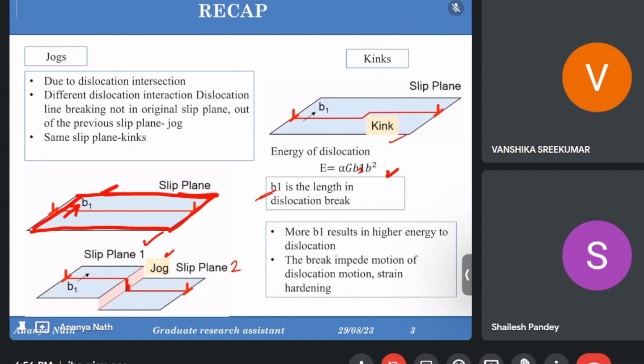Through the interaction of the dislocations, generally they lock each other, which is called the Lomer-Cottrell locks, by penetrating each other, by interacting with each other, by breaking each other. Another thing is this cell structure. When there are a lot of newborn dislocations, the dislocation density is very high inside the lattice, and there will be pile up of the dislocation.